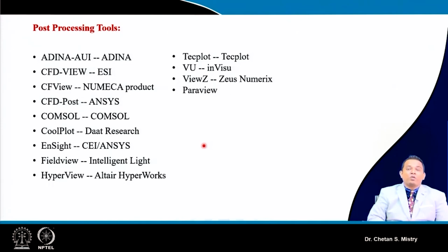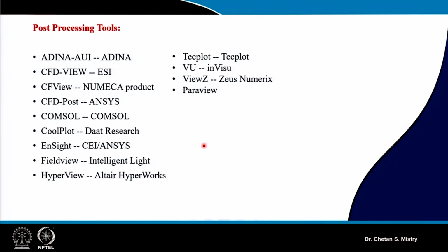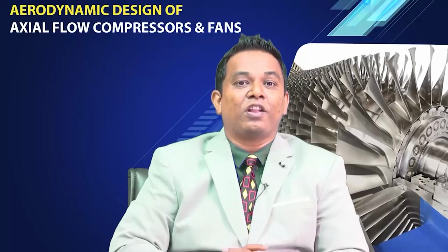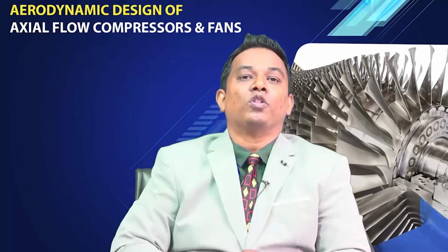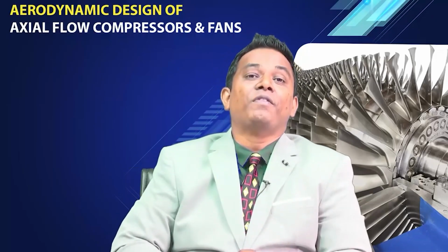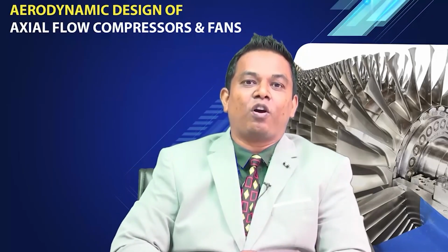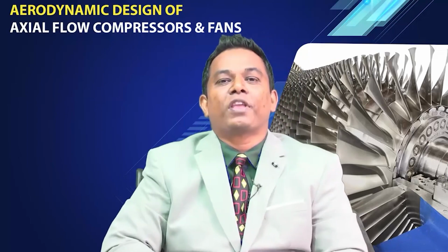So in concluding today's session, we started by talking about different boundary conditions. After those, we discussed different interfaces that need to be selected between the rotor and stator for analyzing the flow through the stage. Then we discussed the selection of different turbulence models.